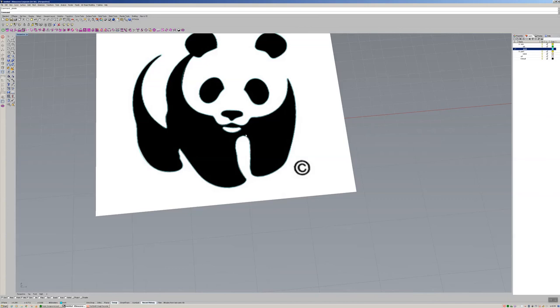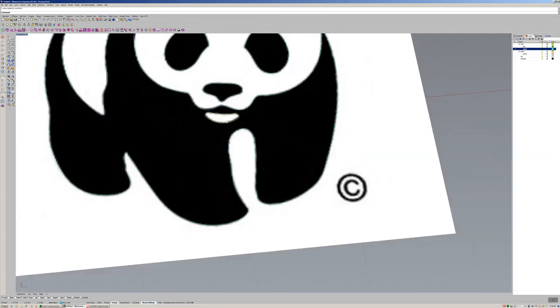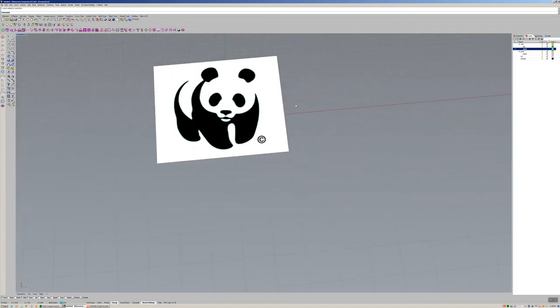So now, do you have that little piece already? Did you outline that little piece? So there it is. You see the little piece? So how do you cut it out? There's a couple ways of cutting it out. One way is we make two objects. One is at 2 millimeters, and then we make that other piece a little bigger, and then we subtract from that piece. It's called Boolean difference. That's the term we use, and it's just a way of subtracting.